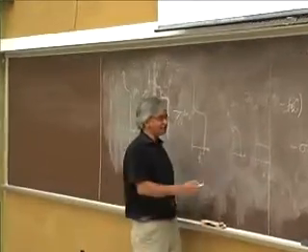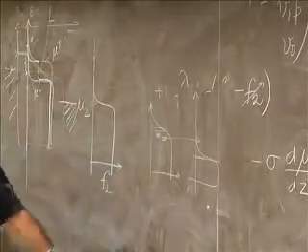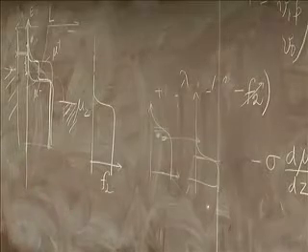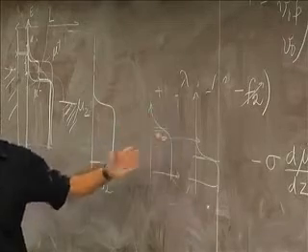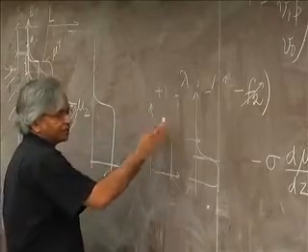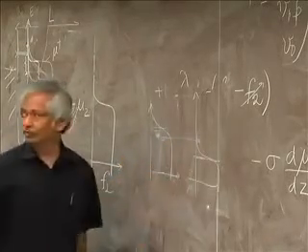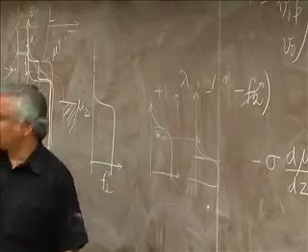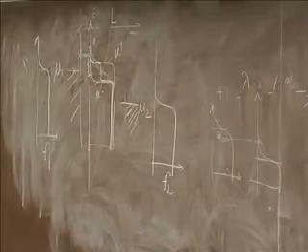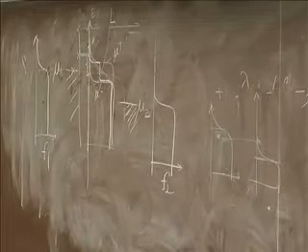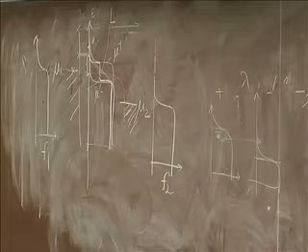And ballistic means what we are assuming is there's nothing to take somebody from here to there. As long as that is true, even with all the inelastic scattering it makes no difference, because this is already a Fermi function. What else can inelastic scattering do to it? Now, once you have things that take carriers from here to there, then of course this will tend to come down and this will tend to fill up a little more. In the ballistic limit, one group is in equilibrium with one contact, another with the other contact. It's really that clear, and inelastic processes won't make any difference at all.